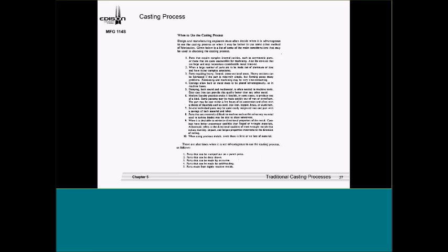As you're looking at that, I also talk about the cost comparison. If I would get a quote for a casting versus a quote for a fabrication, and I have experience with this, I would say, okay, it's going to cost me so much for the casting, but then I've got the machining to do, and sometimes with the machining, you need to allow extra stock for the dross. In other words, dross is metal impurities that will go to the top of the casting, and sometimes they'll cut that off, but you still have some extra machining to do.